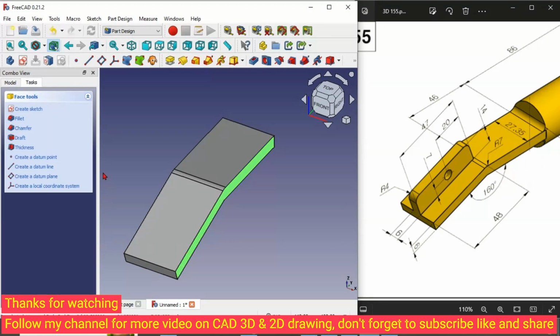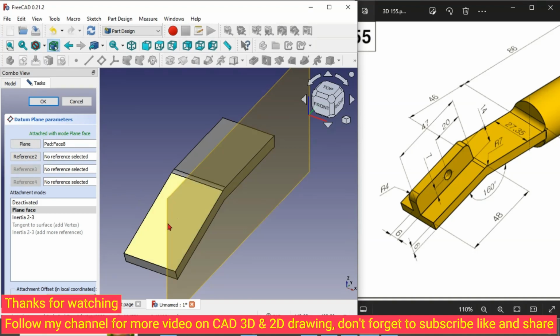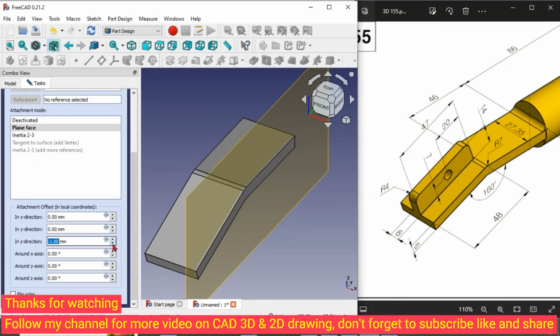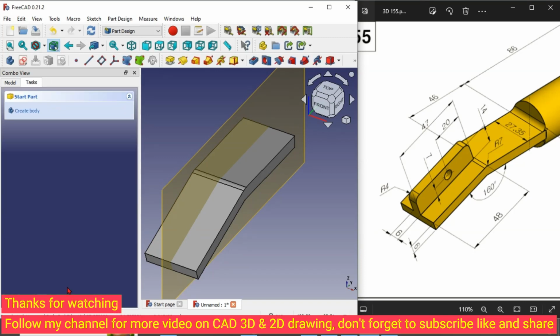So we click here, then we need to change the datum to sit on the middle of this block here. So we change exact direction. Okay, distance from here to here is 27.35. So because we want to move it to the back side, we put a negative. Then 27.35, we divide it by 2. And okay.